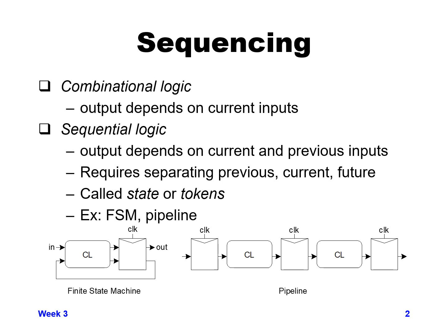Eventually the output of that combinational logic will provide a stable value after a certain amount of time. Once that's stable, we can then have our clock switch again, capture new values in the second sequential, and send that through a set of combinational logic. And so you can see every time the clock changes value, we could have logic going through the following combinational logic till it becomes stable, and then we can have this clock capture it again, and everything kind of goes in a pipeline.